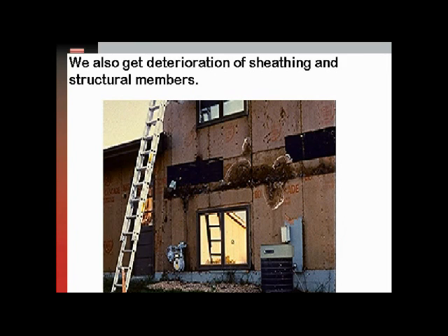So what was happening was that pressurized space was driving moisture-laden air to come in contact with the first condensing surface, which would have been the inside face of the exterior sheathing, and condensation occurred, and you got deterioration of the exterior sheathing. But this is not an air intrusion issue. This is actually a duct leakage performance problem in a building.